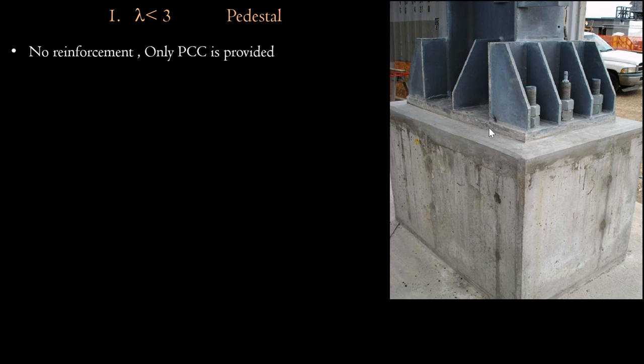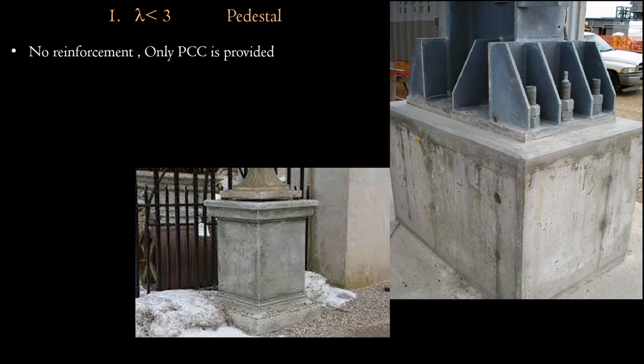This is mainly used for taking the compressive load, for effectively transferring the load which is coming from this structure to the footing, through the concrete. You can see here, this is called a pedestal. It is actually taking the compressive force, but the length or the height is very small.